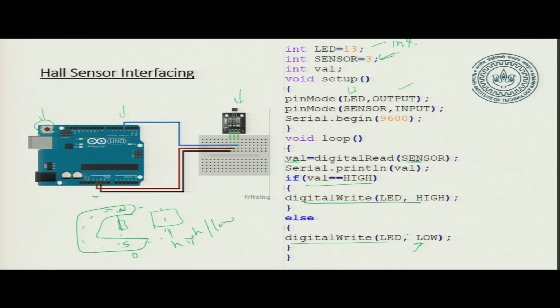So, whenever you bring something here, this is how this works. This is my Hall effect sensor. Suppose we have a wheel, and it has a cut. This is an experiment which we will be doing. This is my wheel and it is rotating about that axis. Whenever this cut comes, this will go off, and whenever the wheel is there, this will come on. So, it is measuring the number of rotations of this wheel. This is not a very good example.